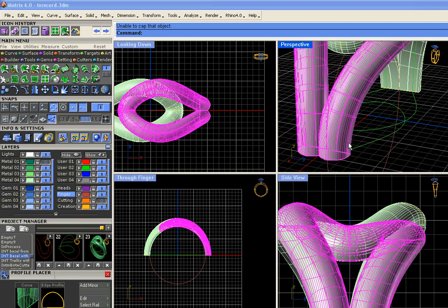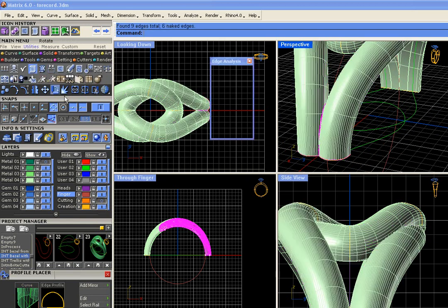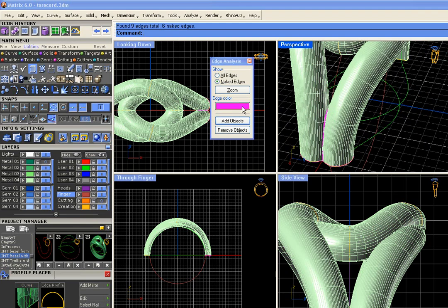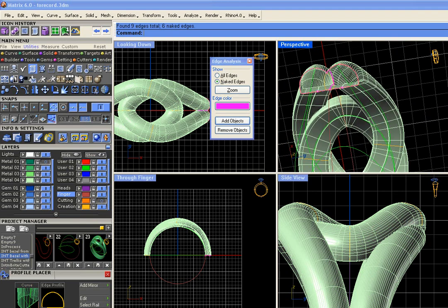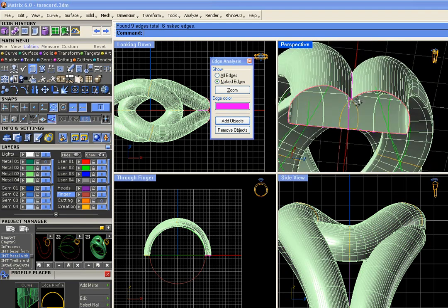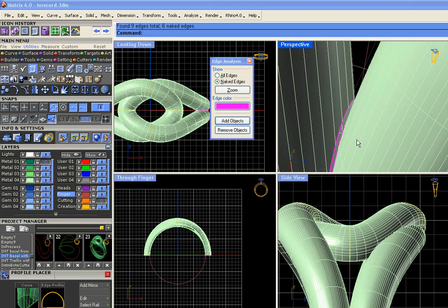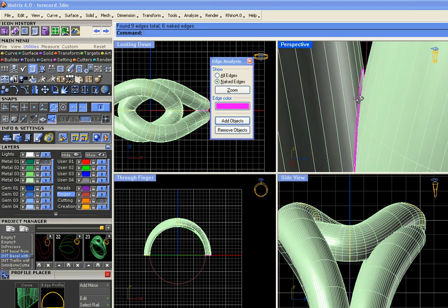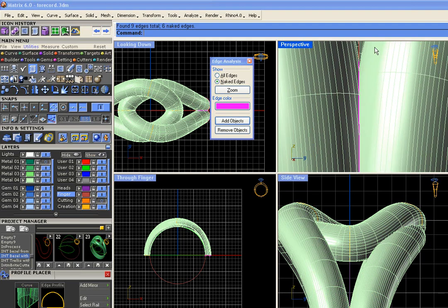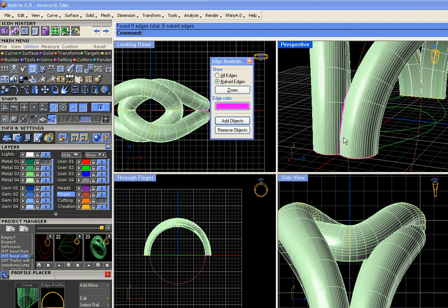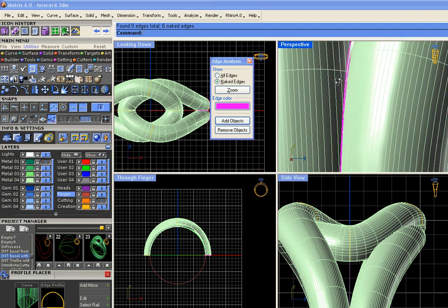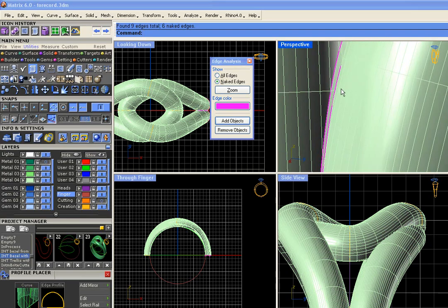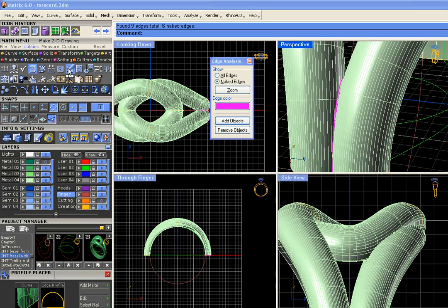Okay, so let's take a look first and look for the open edges. This is the Analyze Utilities command. Here's the Check Edges, and it's going to show us our naked edges. Now, of course, we have the one on the bottom. That's the one we were trying to fix with cap anyway. But here's another whole one, and you can see inside it. Just seems like when these crossed, it didn't like the results, and it kind of fought back. Remember how it didn't split? Okay, I had all these issues, but we can join them up.